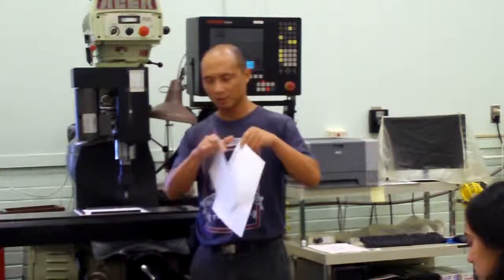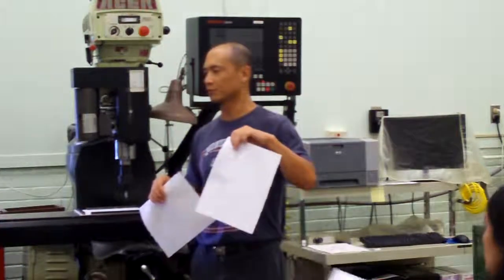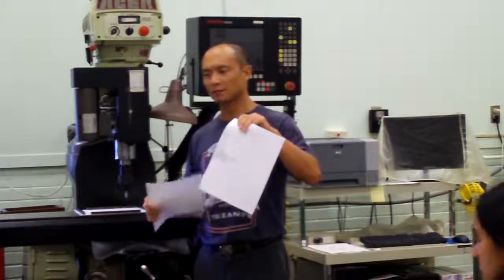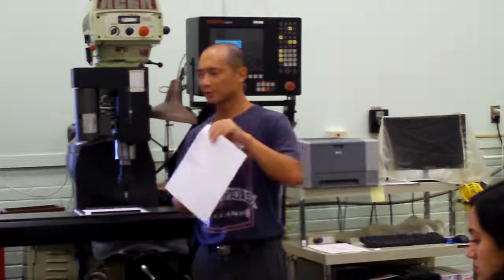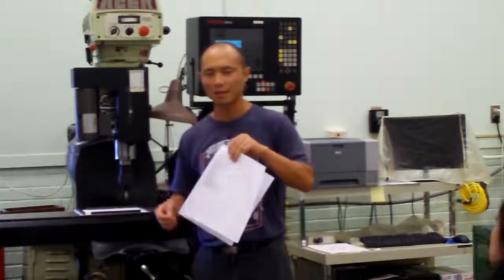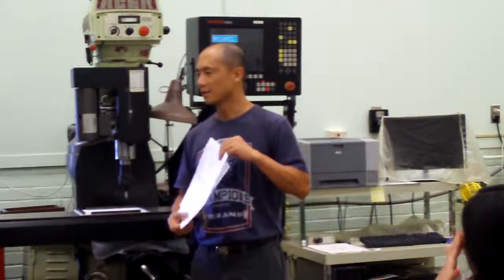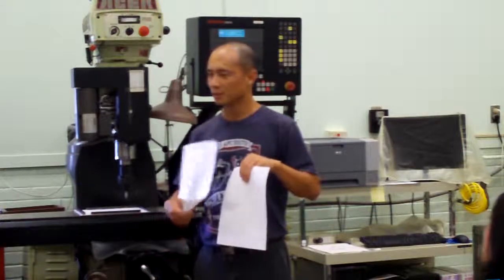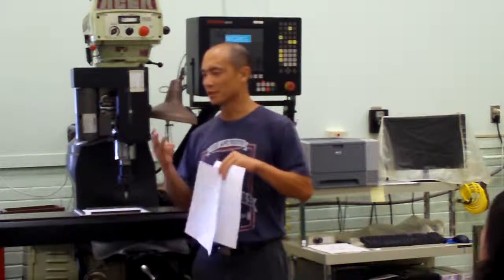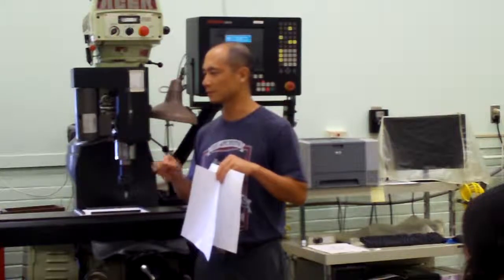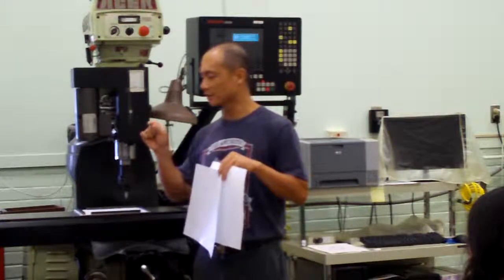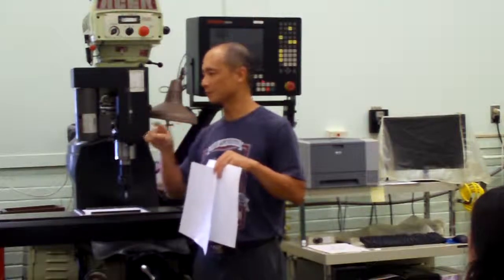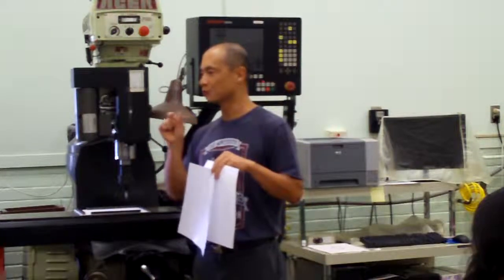That's probably, among all the other codes, the most difficult to comprehend or grasp. As long as you understand how to use G2 and G3, the rest of the G code is pretty easy. And even if you are working with very sophisticated curves, with G1, G2, G3, these three codes, you can accomplish pretty much any curve, because any curve can be approximated by lines if the lines are short enough.